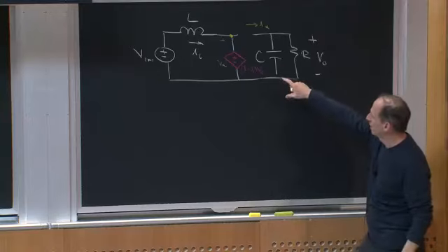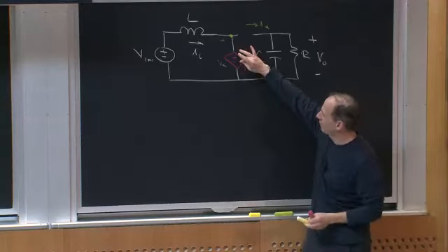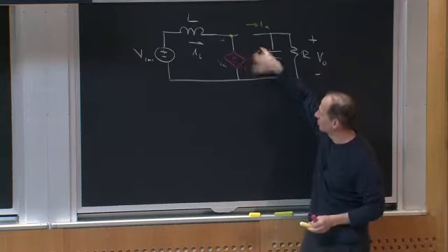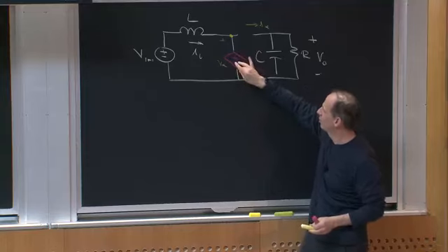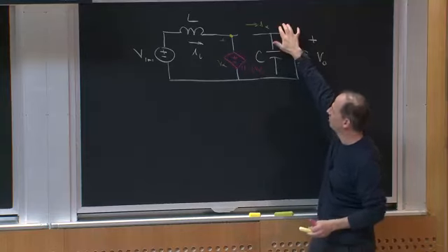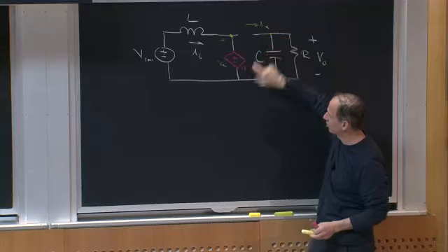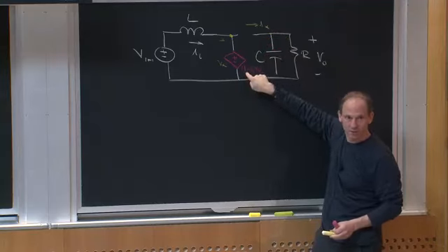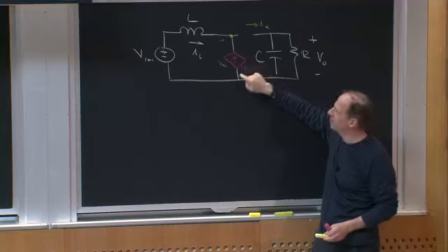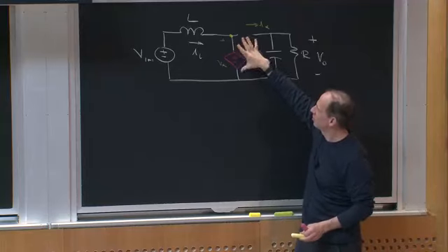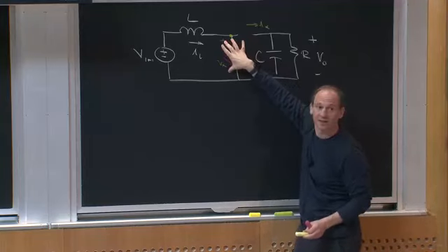Because notice, this voltage Vx pulsates. When the switch is on, when Q is high, it's 0. When the switch is off, it's equal to V out. So in continuous conduction mode, this is a perfectly legitimate representation of what the voltage is doing there.